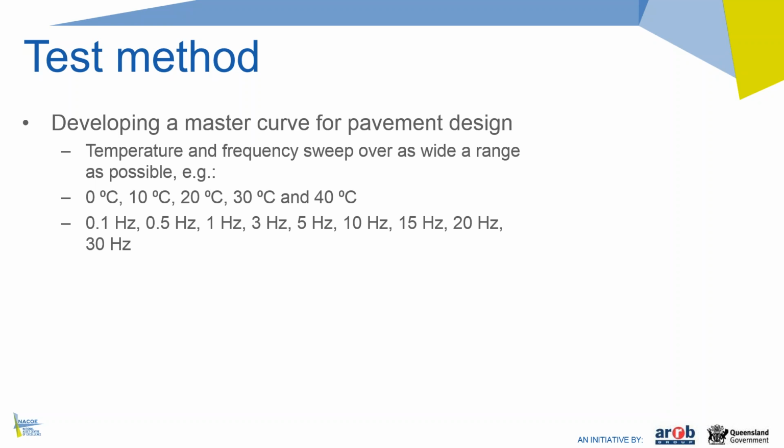It's the same for frequency, so we want to do as wide a range of test frequencies as possible. However, pneumatic equipment is limited in terms of the frequency it can reach, so it all depends on, with your equipment, at what frequencies can you still get a proper and robust load signal into your sample. So pneumatic equipment is slightly more limited than hydraulic equipment in that respect.